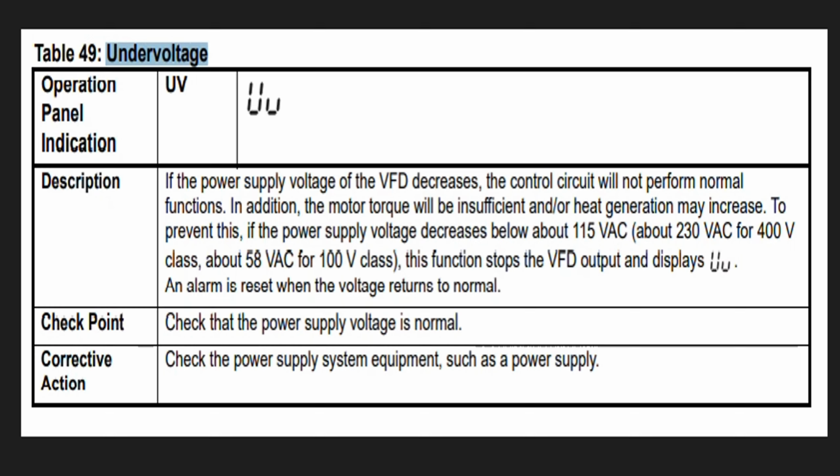Second, you can check that the input power supply is stable. And third, there could be a problem in the measurement section of the VFD. If there is proper input voltage and it is still not measuring properly, this also could be the reason for this alarm.